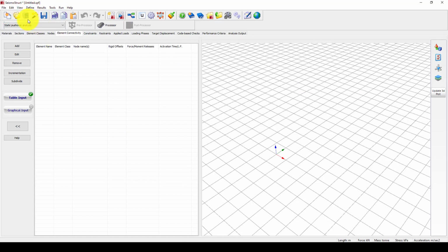Regarding the previous notification which we got at the moment of releasing this point, they said maybe they will not converge. Yeah, the program is trying to use multiple iterations. It reached iteration 32, which in the setting was 100. In that specific step, between 0.1 and 0, it didn't converge. Even though the iteration reached 32, it's called divergence.